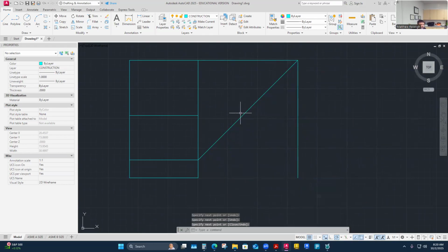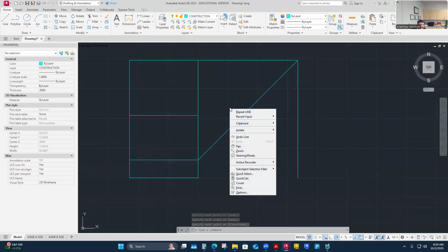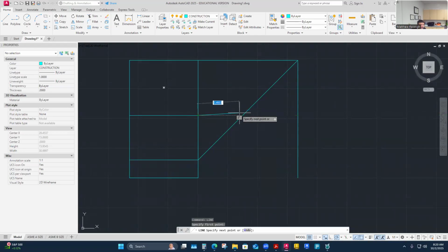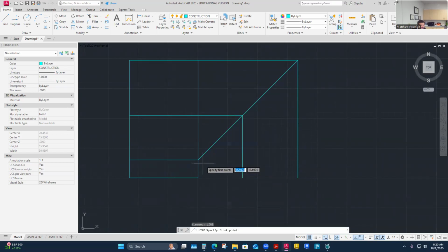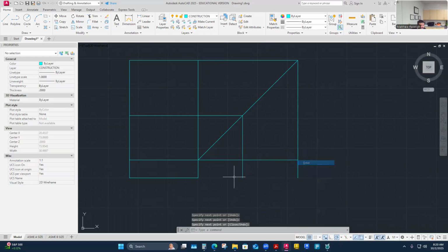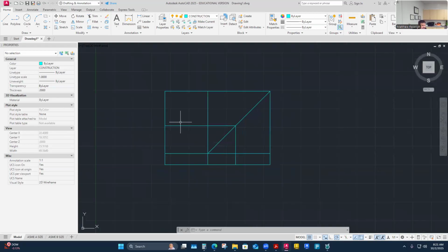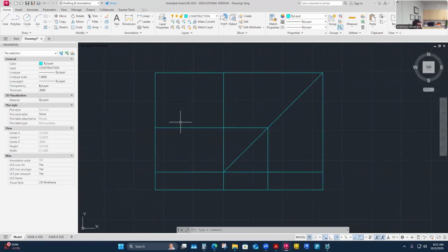Yeah, so spacebar is like enter, right? Some people push enter, so I right click. Mine is like a right click, repeat. Yes, but my hand isn't always on the keyboard because I'm a 3D mouse user, even though I'm not using it right now because I'm doing CAD. I'm a 3D mouser, and you will be too. I'm going to make you one, but not really. When we get into our 3D program, I have my left hand on my 3D mouse, and so I'm a right click enterer. But yes, spacebar acts as enter. It's like exiting the command and re-entering the command, just like enter would. It functions the same. Good point though, because some people prefer that. Maybe their hand is more naturally positioned on the keyboard.